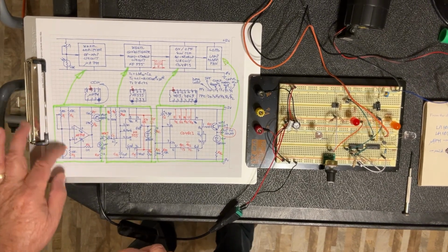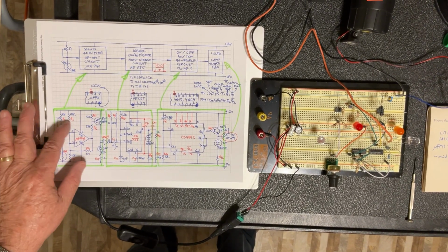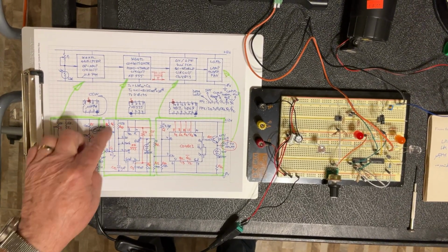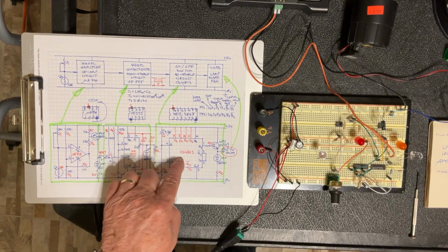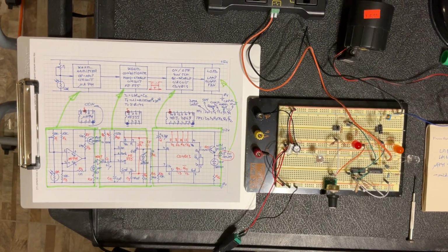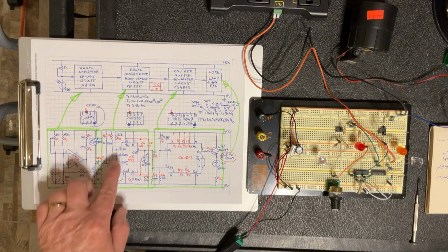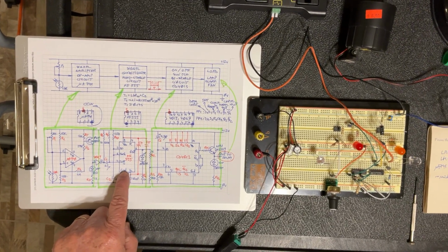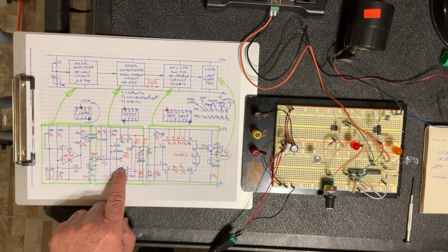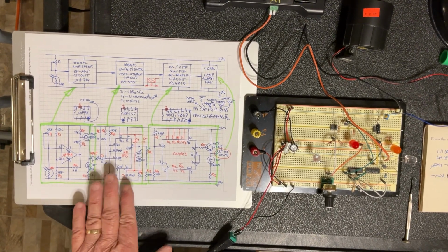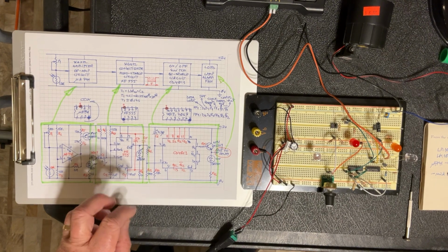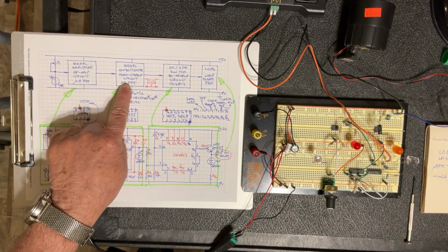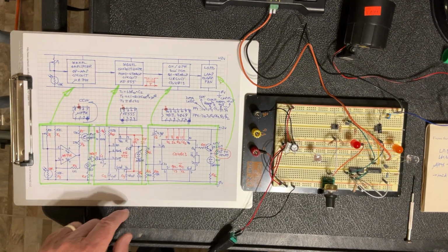So I won't discuss this stage anymore because we've done it last time. It's the signal amplifier. I'm going to discuss the signal conditioner and then the on-off switch, how to make it. The signal conditioner is made using a very common and famous circuit, a version of the 555, and is arranged in the shape of a monostable circuit, exactly like you can see on the block diagram.